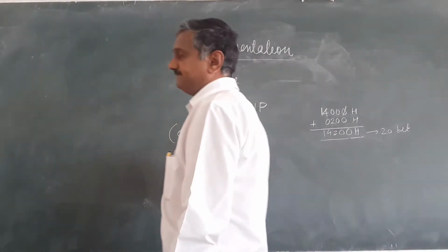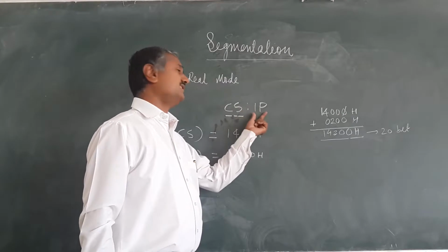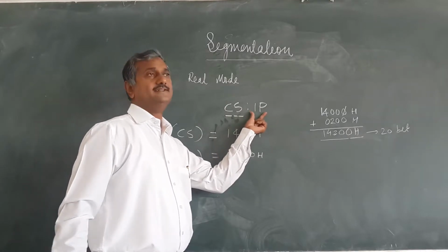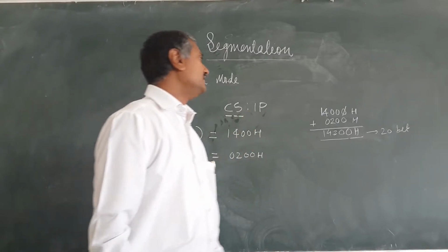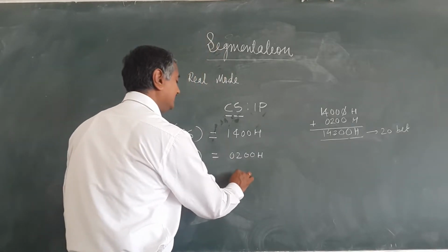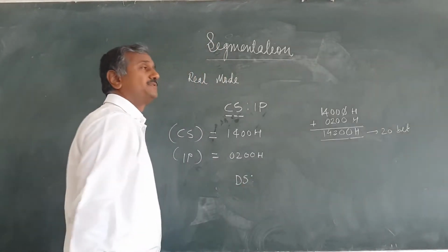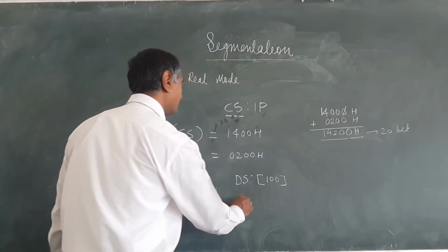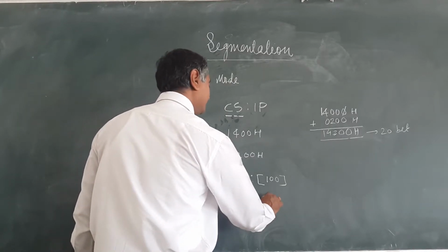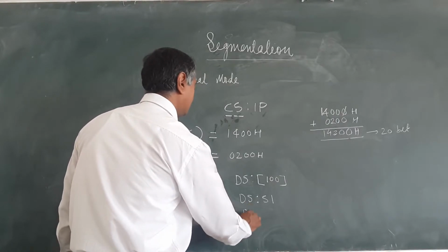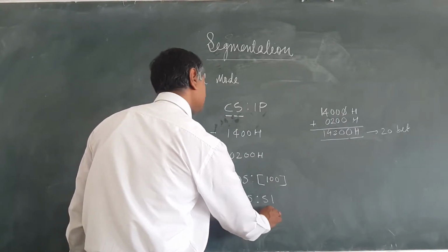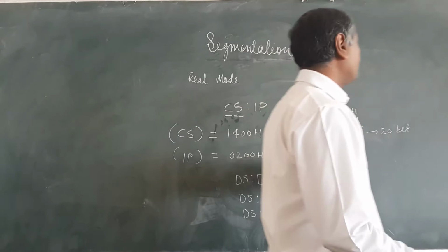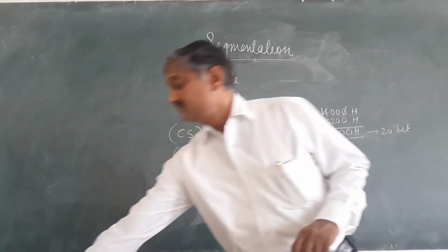Whichever segment the system is referring to and whichever offset, this particular pair of segment register and offset will vary depending on the type of access. For example, if you are accessing the data segment, by default DS is used and the offset can be a direct address like this, or it can be in the form of an index register like this, or it can be in the form of a pointer register like this also. So by using this pair, the system calculates the 20-bit physical address.